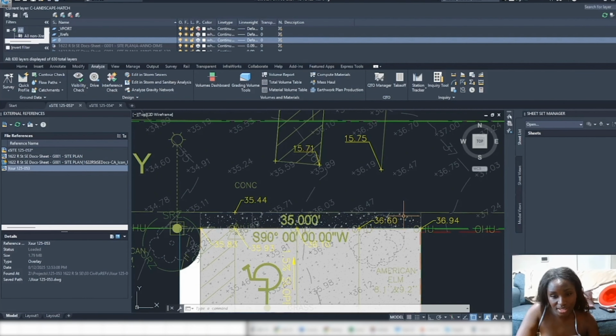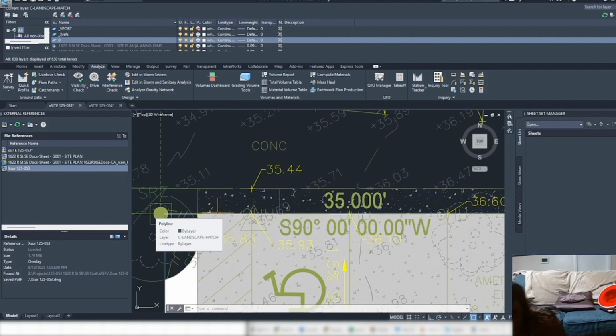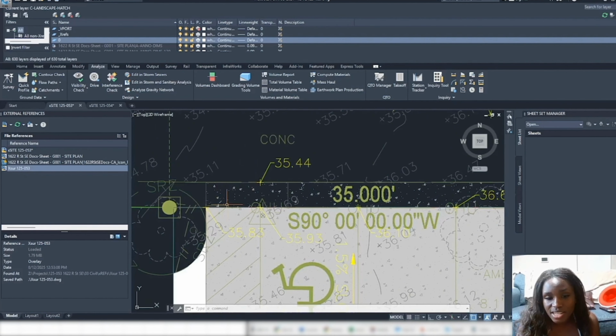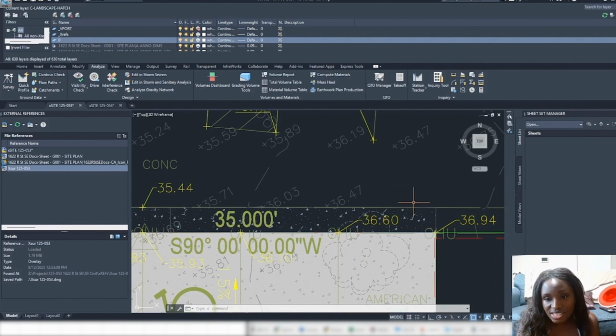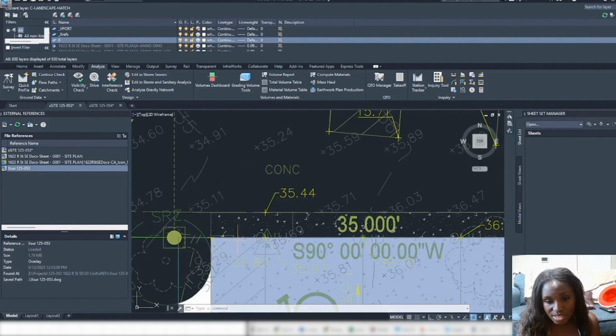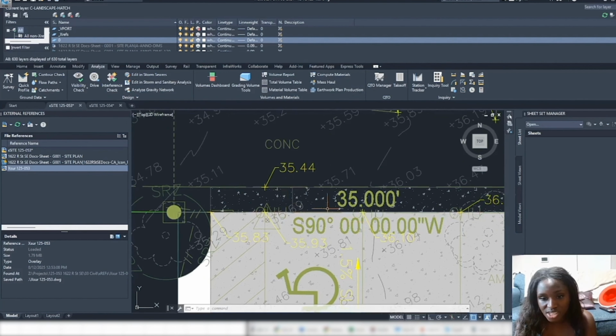So we're turning it around. Like I was asking, it will be ramping from the other side. But how will the other cars be entering the parking spot if it's ramping from their side? It will still be ramping up here. It will just be less steep, because here it's not as steep of a ramp. It's just a 2% cross slope. Here it gets really steep. Yeah, because we need that 1% cross slope, and that's why it made it more steep, because we had to lower it here. But if we just lower it here, we end up being steep here.